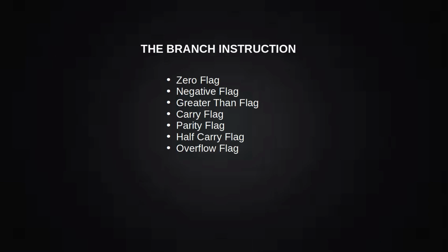You can have a parity flag, which is used to indicate the parity of an integer. You can have a half carry flag, which indicates a carry between bits 3 and 4 in a byte. That one is actually very useful in binary to BCD instructions, by the way. You can also have an overflow flag, which is like the carry flag, but it takes the input's integer sign into consideration. There are other flags you can include as well, but those ones will usually cover most conditions you would want to concern yourself with. Which ones you want to add, though, is up to you.